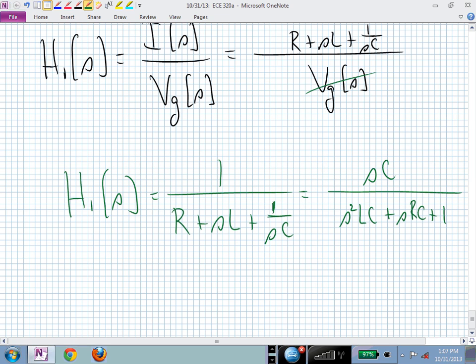And you could have known that by just, somebody gave me an RLC circuit. I have positive resistors. That's just going to dissipate energy that I put in. It's a stable transfer function. But the denominator is now the roots of that quadratic. And that quadratic, depending on your R, C, and L, could be 2 real roots, or it could be 2 complex roots.